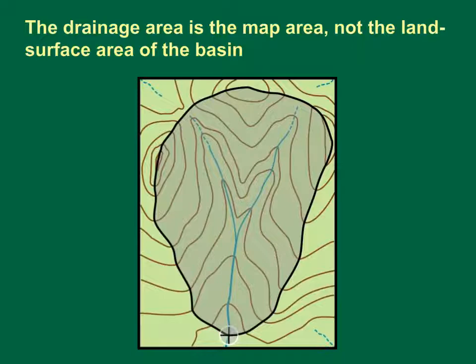For example, researchers noted that sewer drainage delineation for Malice Creek in Michigan more than doubled the drainage area from about 3.9 to 8 square miles in comparison to topographic divides. In another study, researchers used GIS coverages to delineate small urban catchments, and they discovered substantial differences in drainage areas greater than 20% in 17 of 18 basins on the basis of differences between expected and measured median runoff coefficients. In that study, differences as large as several orders of magnitude were confirmed by obtaining detailed drainage plans and doing site inspections. However, we will only consider the more common case for many basins in which the topographic divide is sufficient for our initial estimates.